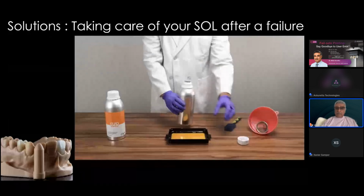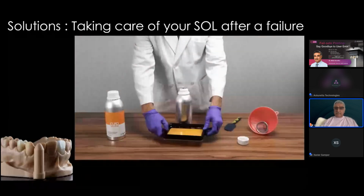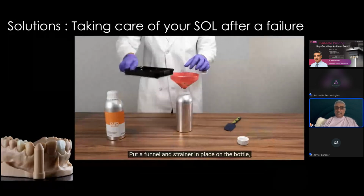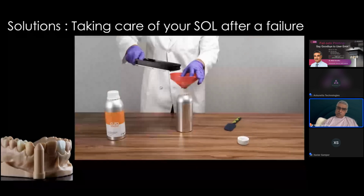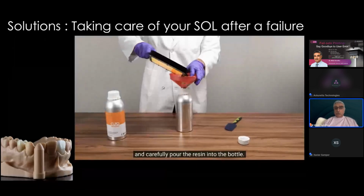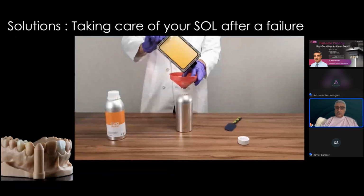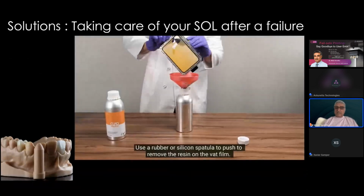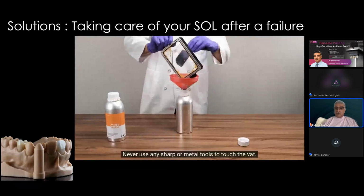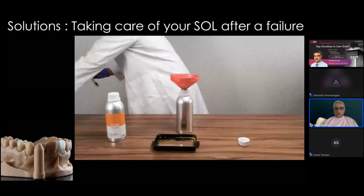Make sure you pick the right resin bottle, of course. You pick up whatever resin is left behind in the vat, use a funnel, get a filter into the funnel, and pour the resin through the filter, through the sieve. What happens here is any particular debris is filtered out by that filter. After that, you need to use a rubber spatula, easily obtained in any cooking item store, and you can clean out all the excess resin, put your bottle away,